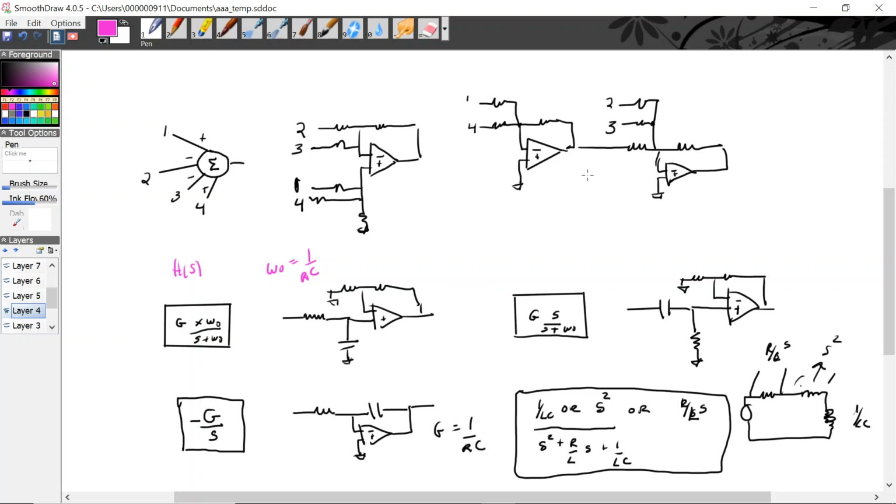And that's actually about this here, and telling you to add another stage in series is actually on the next slide. And then there's some other things where we have an RLC, and I'm trying to say this as succinctly as possible. Because these are all in series, no matter where I take the outputs, across the resistor, across the inductor, and across the capacitor, the denominator is going to be S squared plus R over L times S plus 1 over LC.